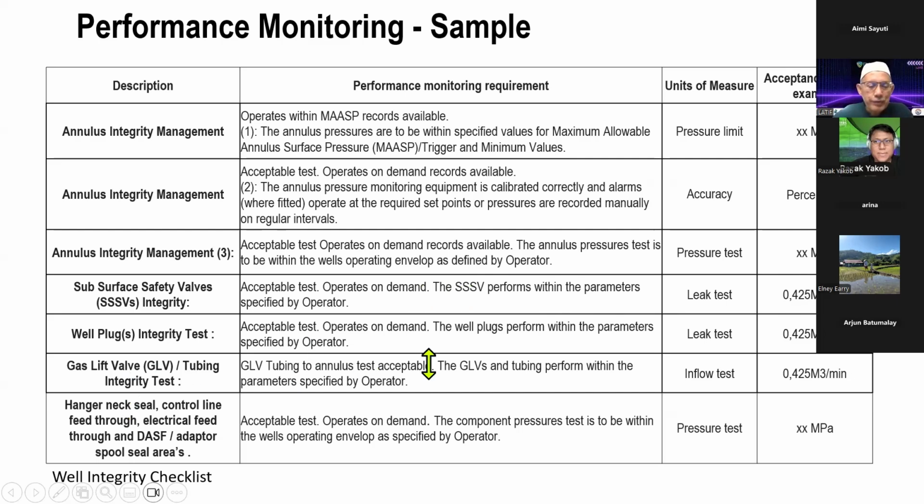So yeah, gas leak valve check, and the hanger neck seal is at the top surface. So if there is a leak, you get exposed directly to the hydrocarbon at the surface. So it's quite important as well. But normally we can have the TRSSV closed so that we can do the repair of this neck seal. Okay, by installing the bridge plug in the wellhead, and then the two-way plug, called the solid plug, and then we can close the TRSSV and of course they have two temporary barriers to do repair.